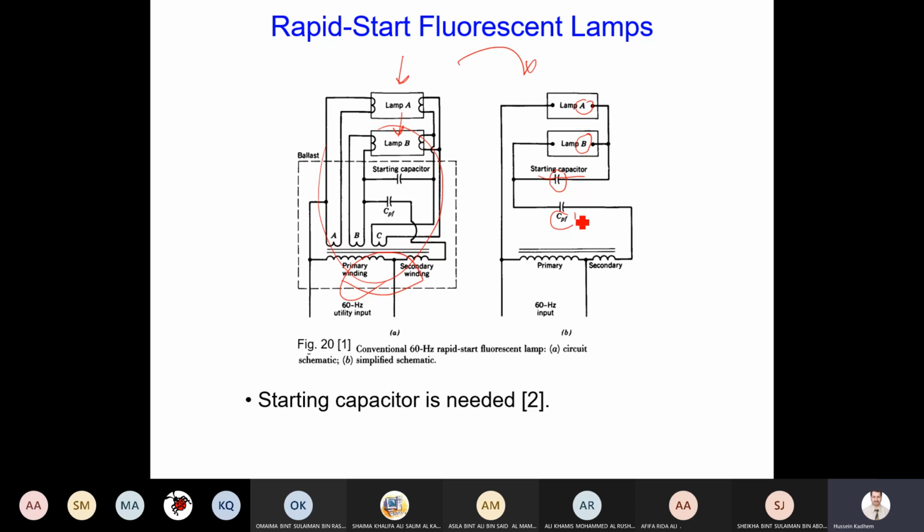Why does it correct the power factor? Because we have inductance in the circuit which absorbs reactive energy. It means the power factor will go down. With a capacitor, it will produce reactive energy, so it goes up. So we compensate, let me say. And this is my inductance, as you can see here. Let me tell you how it works.